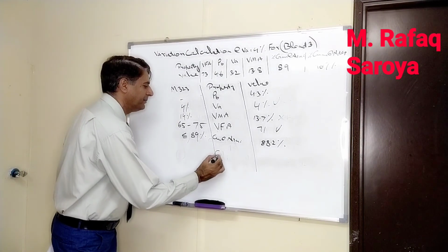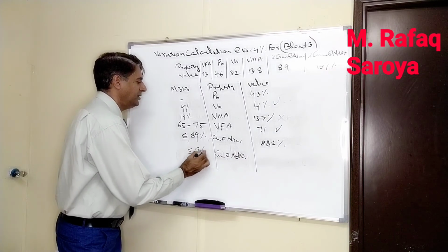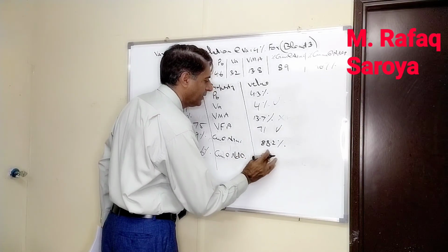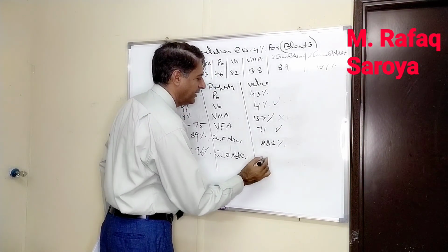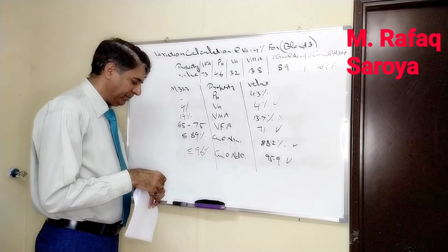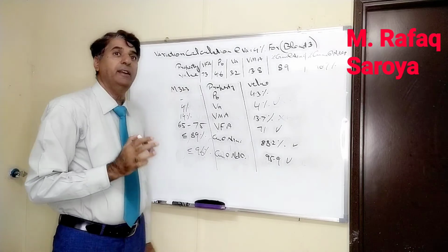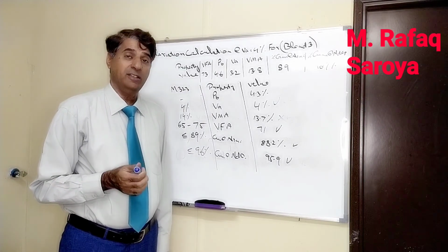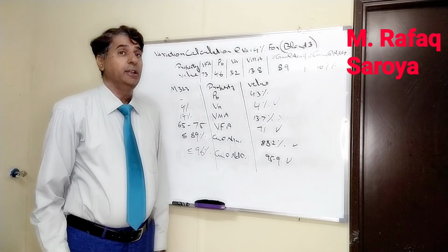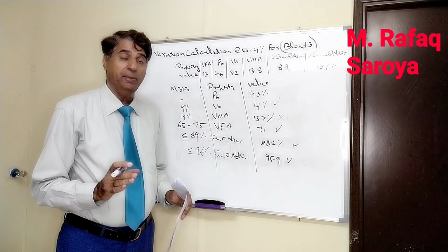Similarly, GMM at the rate of N dash final is 96%, and my value is 95.9, which is also compliant. So keep this in mind: if any value given in the Superpave specification is not complied with, that blend will not be acceptable. Up to now, we have made three blends, blend 1, blend 2 and blend 3.